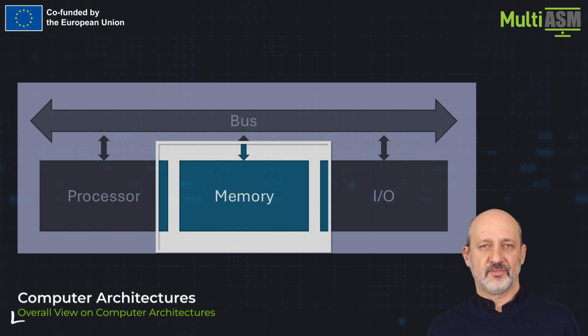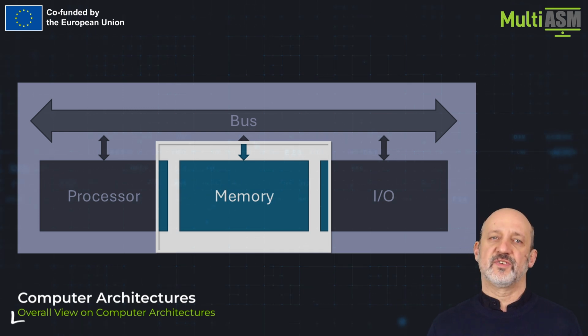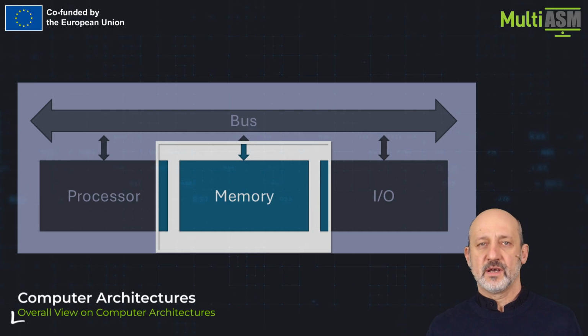equals 256 terabytes. The size of the memory installed on the computer doesn't have to correspond to the size of the address space. In PCs, we usually have a few dozen gigabytes, which is less than the address space of the processor. On the opposite side, in constrained devices, the size of the physical memory can be bigger than directly supported by the processor.